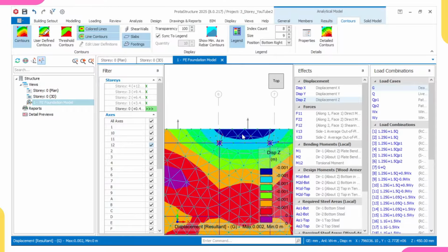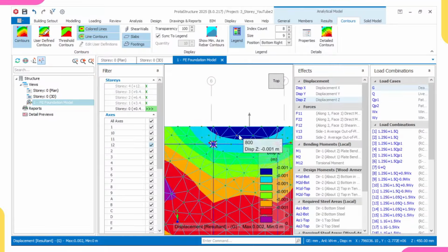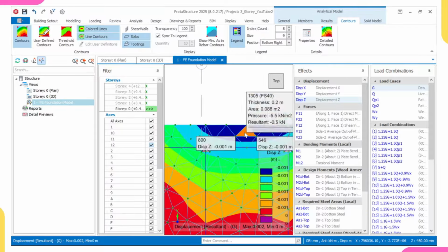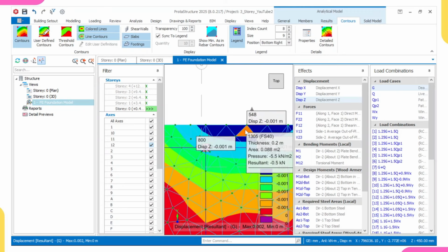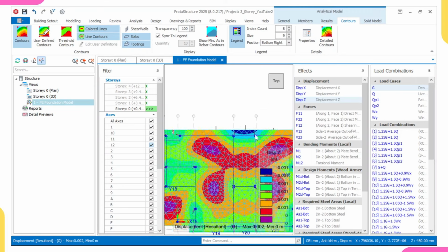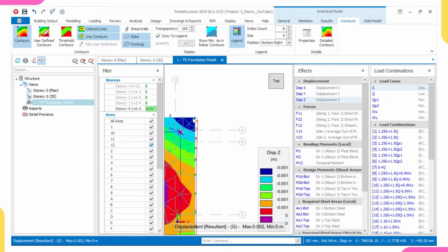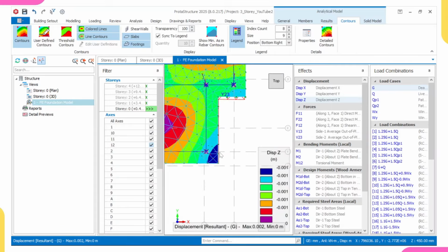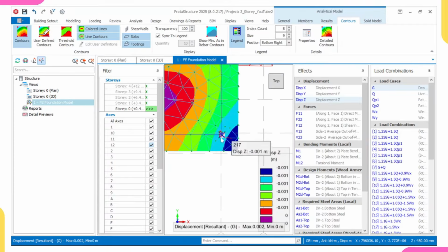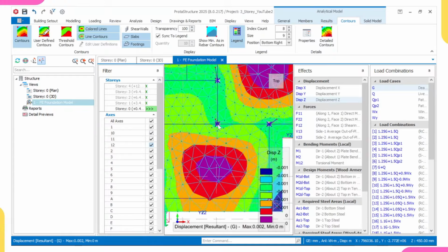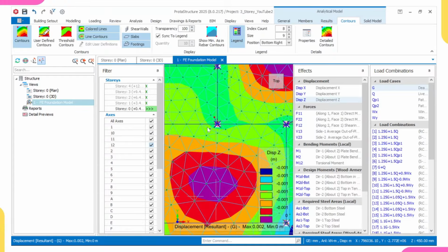We're having a column here, so here is blue. Assuming I increased the cantilever slab, assuming I made it something like 1800, the load coming to it will be lesser, because that cantilever slab will be able to distribute its load to the soil. So let's just continue the analysis. All these edges are blue in color, meaning that the load coming to these edges is very high. The reason is that this column does not distribute its load very well to the soil. If you look at all these center columns, they are just green, because their load is distributed to the soil evenly. The top slab around it helped in distributing its load to the soil.